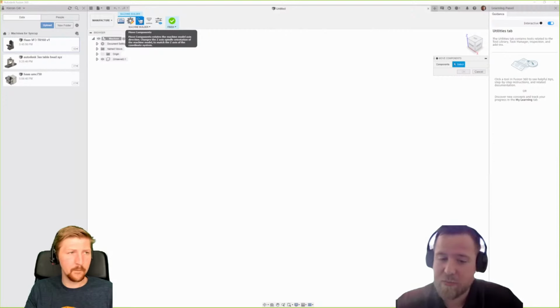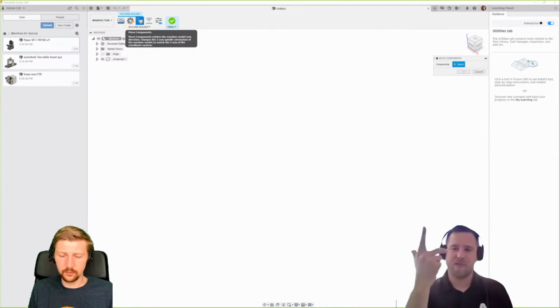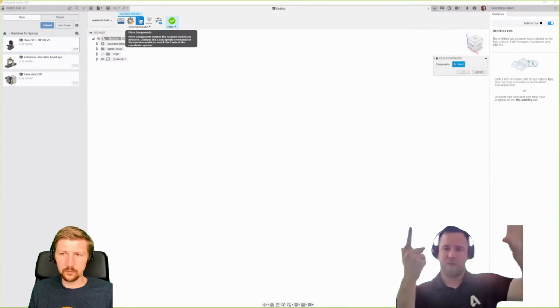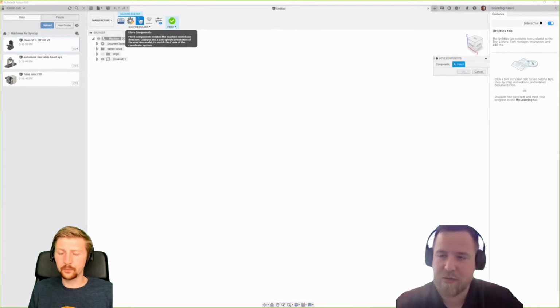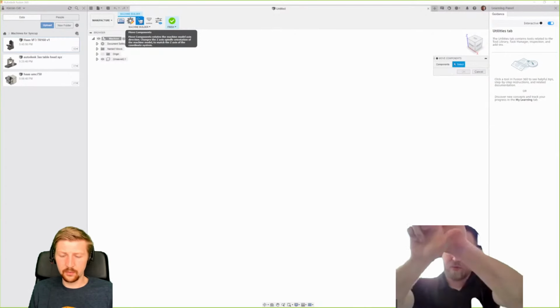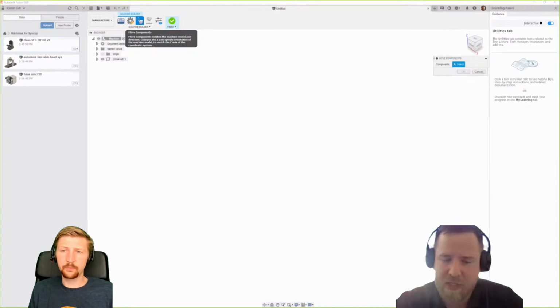The only thing that machine simulation requires is that the z-axis and the major orthogonal axes are going in the correct locations. So even if your triad's in one location and your machine's over here, providing your z's going in the right direction, then you can continue with that rather than having everything lined up perfectly on the table. So there is leeway for that.